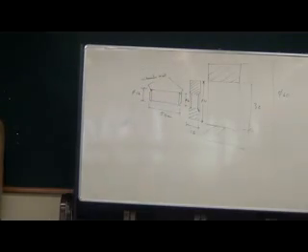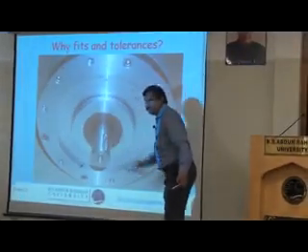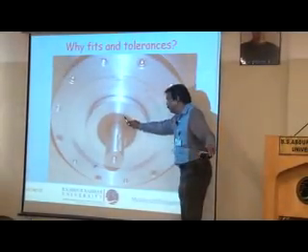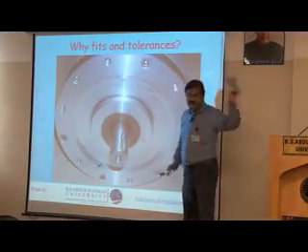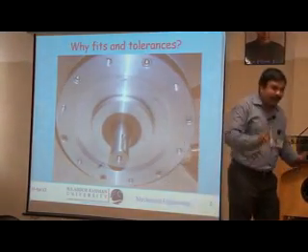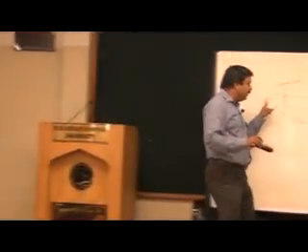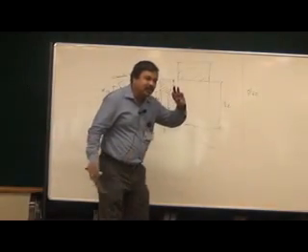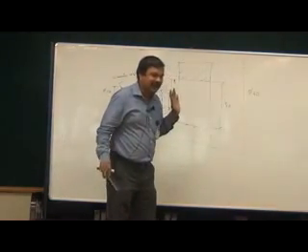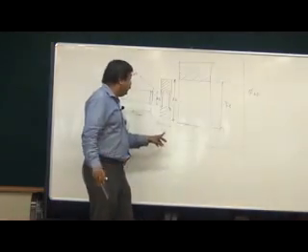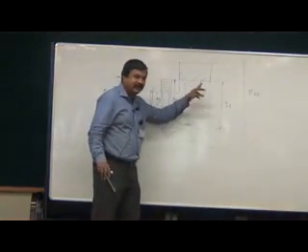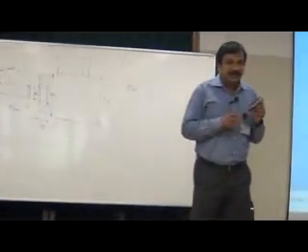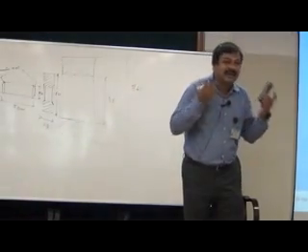So the 16 mm shaft is this, and I am talking about this part alone. These details I have not bothered. The bush drawing I have given, the housing drawing I have given. Now my problem is, in between this 16 shaft and the 16 hole, it must rotate freely. Then only the shaft will rotate. On the other hand, between these 32 mm diameters, there should not be any relative motion. Now, how am I going to realize this?